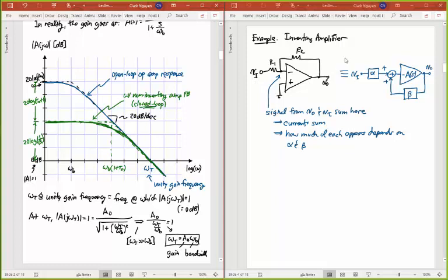Like last time, I wanted to do this with the intuitive approach. With this intuitive approach, what I'm trying to do is take the circuit and equate it to something that I know to some extent, and I think you've seen before, a system block diagram of a feedback circuit. We analyzed this last time as well in case you had not seen it. This is different from the non-inverting amplifier because I've got this resistor going from the input to the negative terminal of this op amp, which I call the summing terminal here, because what it does is sum currents going through R1 and R2. We talked about that at the very end of the lecture last time.